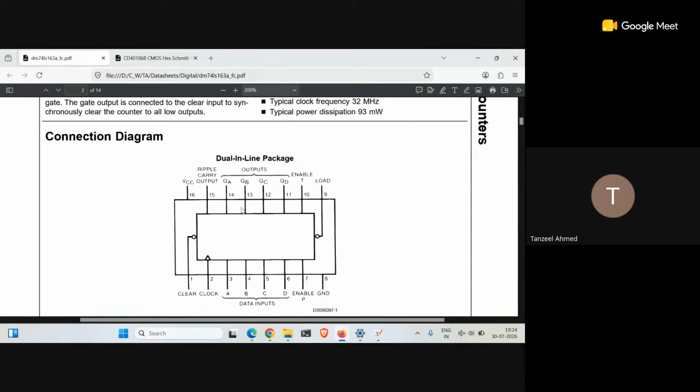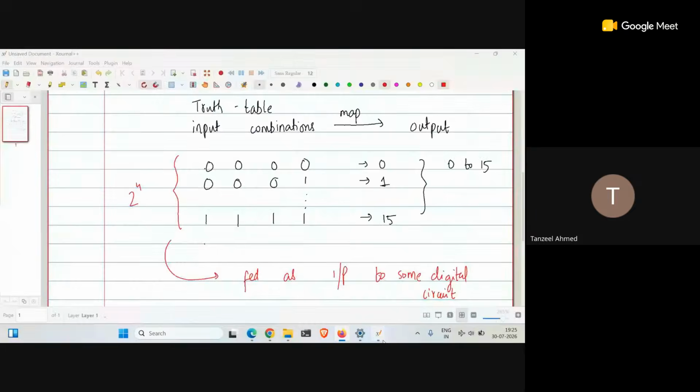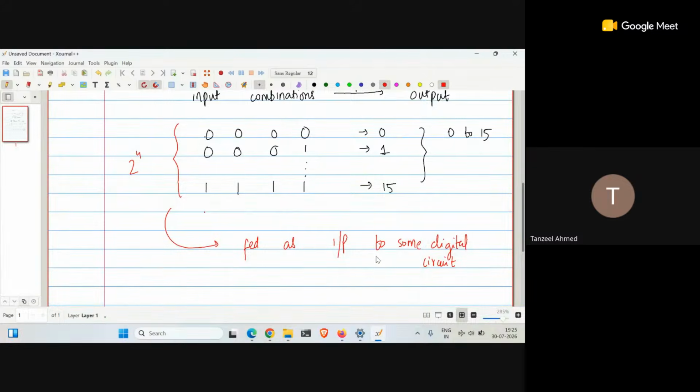Immediately you won't be able to see what to do here, but it would involve setting this clear pin to a low. So this clear pin actually stops the count and sends you back to 0. So if your clear is sending you to 0, and simultaneously the load is asking you to load from here, then you can come back from 9 to 4. And how we can do that, let me just show some example.